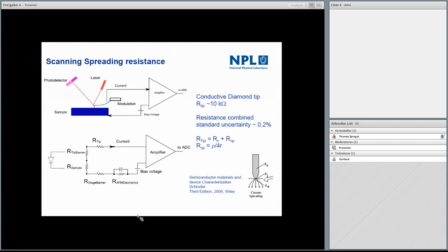You know, here the keyword is resistance, because if you want to go from resistance to resistivity, depending on the model, but usually it's more or less an inversely linear relation between resistance, resistivity, and the contact radius between the probe and the sample. And this contact radius, we don't know. The uncertainty of the contact radius is enormous, and really could be 100%. So, you know, I can give you a resistivity that matches exactly the value in literature because I choose the R accordingly.